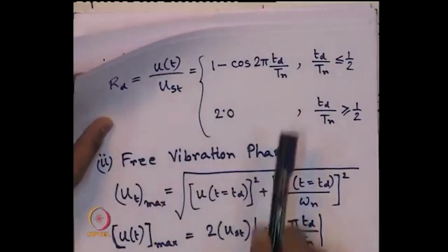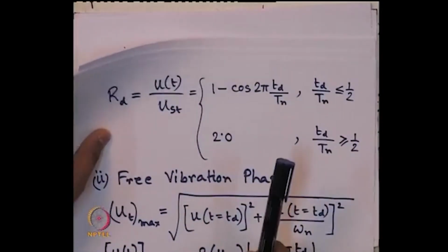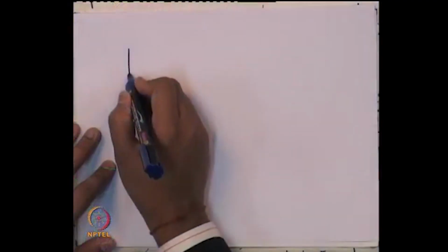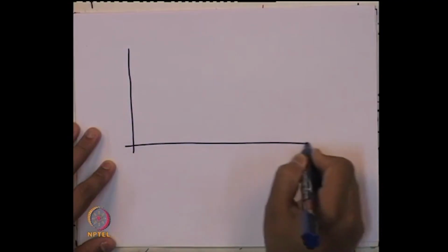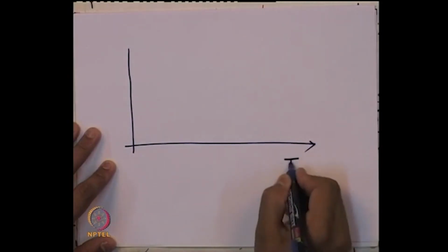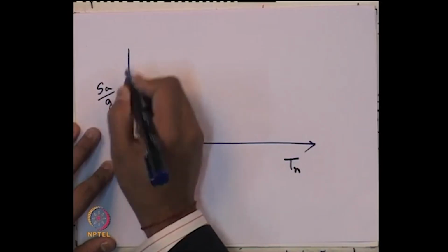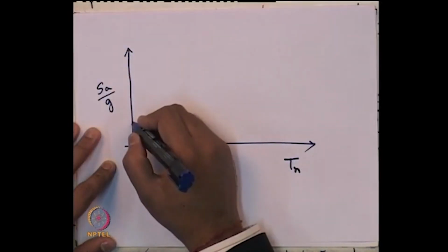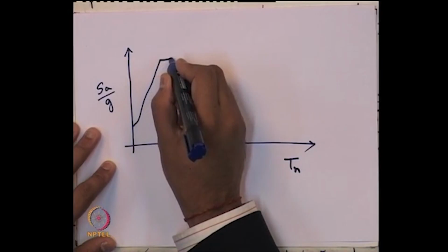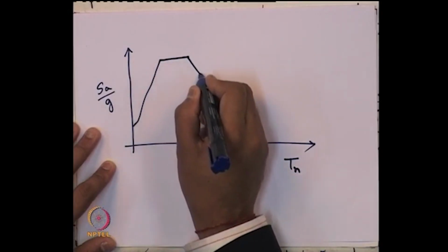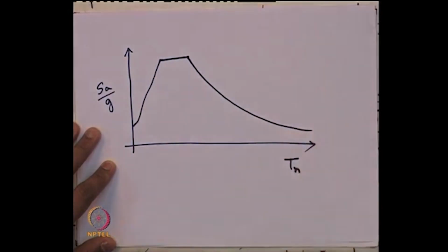So, that is the reason, if you see over here, here I have not considered the damping portion, but if you consider the damping portion, if you remember my soil dynamics lectures, the typical plot of the response spectra, which we show as Tn and say Sa by g, it can be acceleration response spectra, it can be displacement response spectra, it can be velocity response spectra.